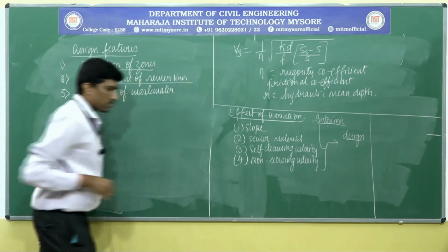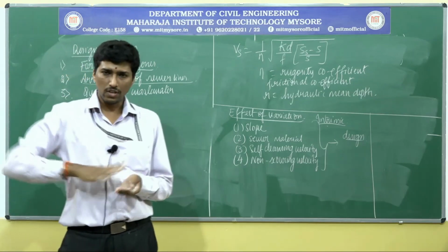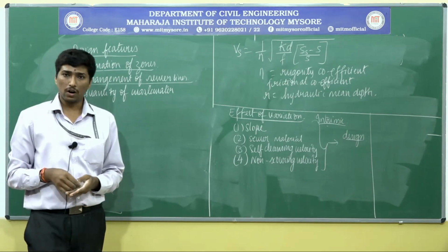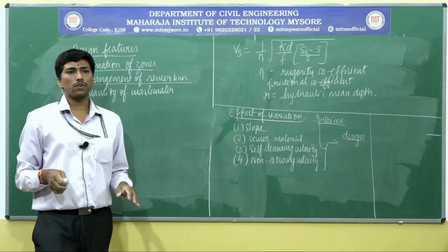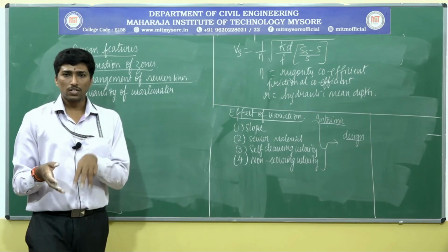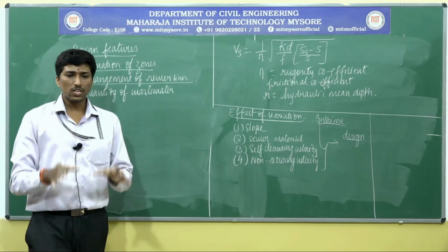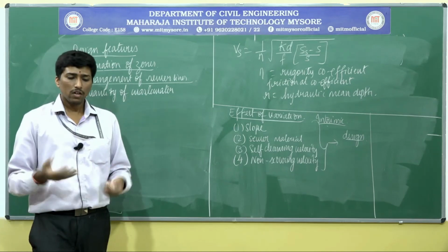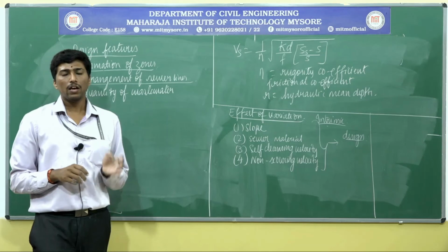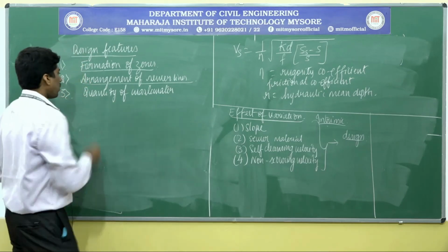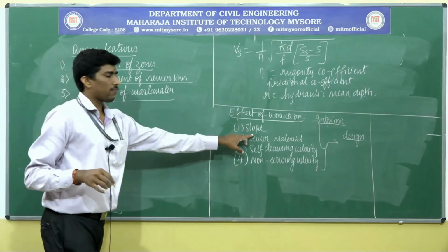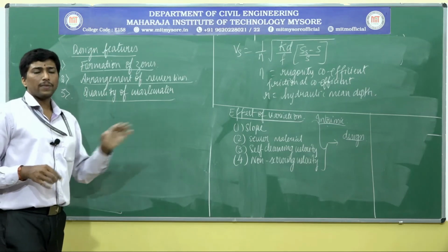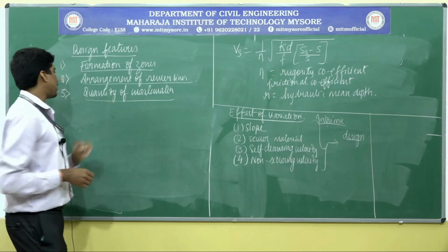And one more thing, the arrangement of the sewer lines. Sometimes during the outfall, if you want to construct the wastewater treatment plant at a higher elevation, a pumping system has to be adopted. Or maybe at the lower elevation itself, a large depression is made where the outfall is created, so that the sewage being carried and flowing at the bottom, like a well, is pumped into the wastewater treatment plant and sent to the equalization basin. Quantity of the wastewater, as I told, depends on the effect of the variations: in the morning, evening, as well as on holidays, the wastewater tends to change.